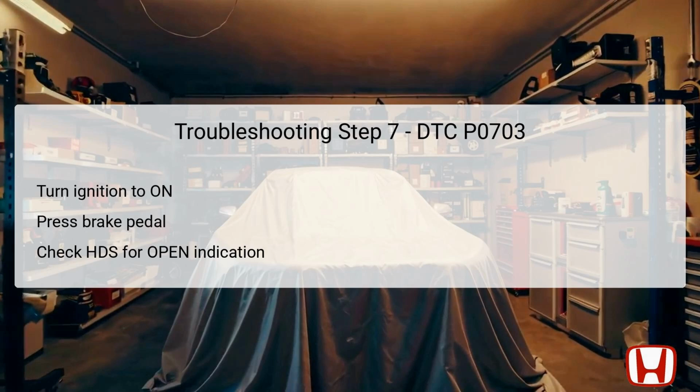This can occur if the connections are loose or exhibit poor contact. It is crucial to check for any potential loose terminals or poor connections at both the brake pedal position switch and the PCM. Should the system have freeze data or an onboard snapshot of this DTC, attempt to replicate the failure under similar conditions to ascertain whether it's a persistent fault or an intermittent one. Accurately gauging this signal is critical for determining the next course of action in addressing DTC